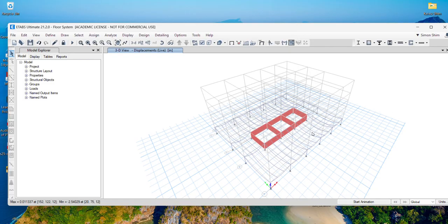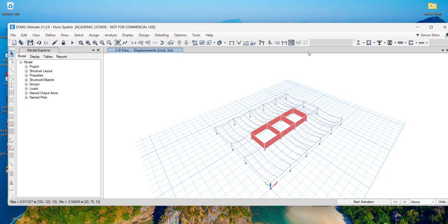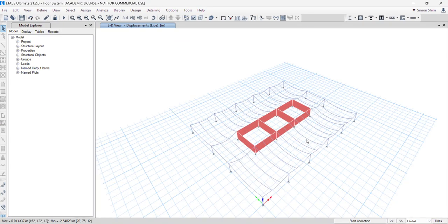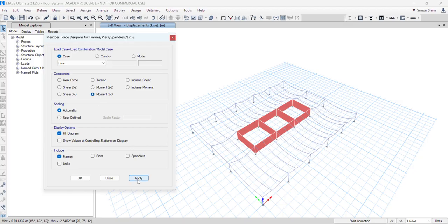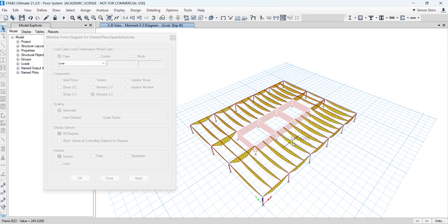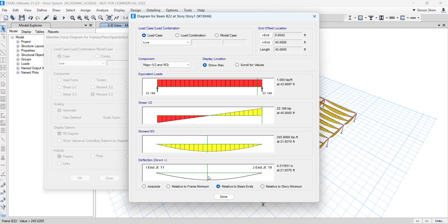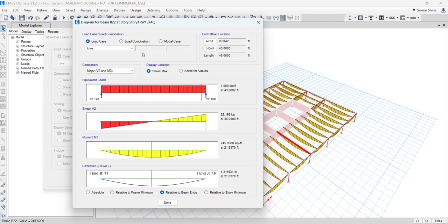This beam deflection, Control D. So let's say this, and if you click this beam, let's click to show the moment. Click the beam. So here, when you look at the deformation shape from deflection, you see the deflection at 4.3 inches. This is pure steel deflection under the live load, right?